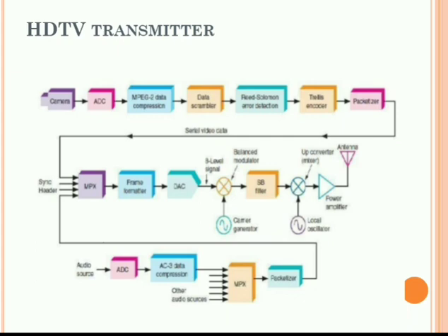channel arrangement system. Here, each audio sample is converted to an 18-bit digital word, and the audio information is time multiplexed and then transmitted as a serial bit stream. A data compression technique that is designed for AC3 will be used to speed up the audio transmission.